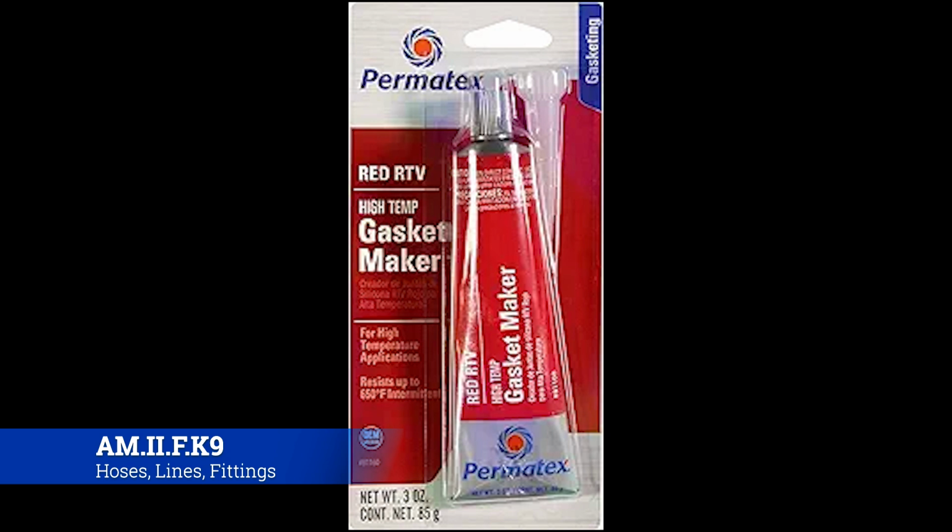And a little bit of this goes a long way, because you can just squirt some RTV on it if there's two clamps or two hoses coming together that you can't seem to get to stand apart in any meaningful way, or you get into situations where if you move this hose, you solve one problem but create another. RTV can be a way that you just shoot it onto the hose. It'll set up and create a little rubber buffer zone between those two hoses and save them.